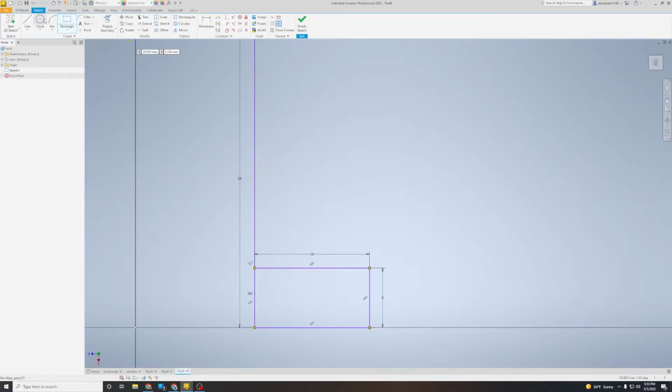I'm going to use the arc tool next. The arc tool is found between the circle and the square tool. The arc tool requires 3 clicks to place an arc. The first 2 clicks place its endpoints, and the third click defines how strong or how weak the arc is. An arc is a partial circle.